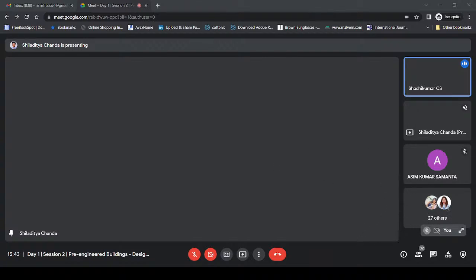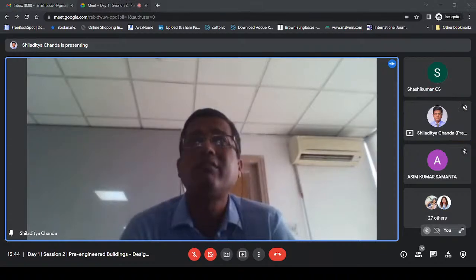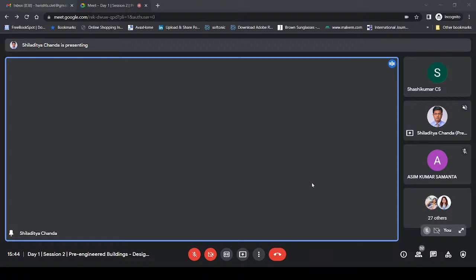Regarding this hillside washer, sir, can we provide the regular bolt, or is it a must to use hillside washers? Sir, in the regular thing, a hillside washer is better because that fits better. Since your bracing is intersecting the flange in an angled way, your normal nuts may not fit tightly. With the provision of a hillside washer, you can have a snug tight condition over there.